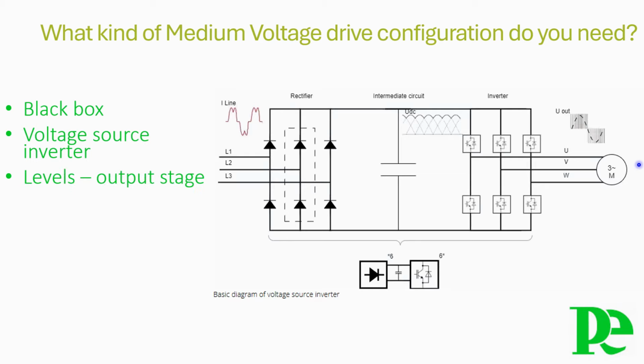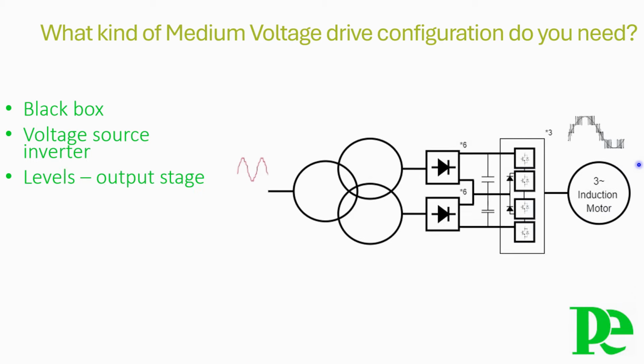And yes, this is a three-level drive. Notice that the phase-to-phase output voltage of the three-level inverter is made out of 5 steps and is already looking much better than the two-level output voltage.